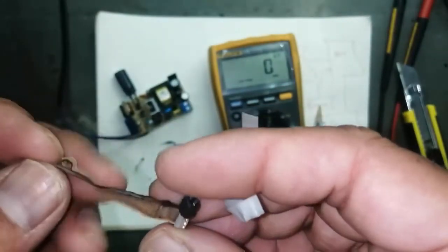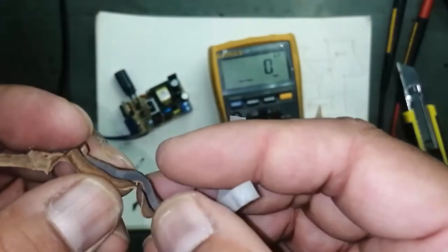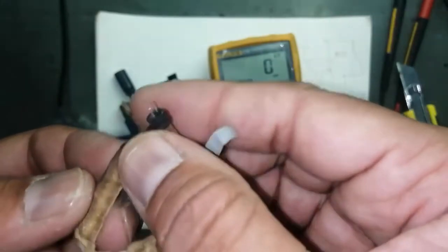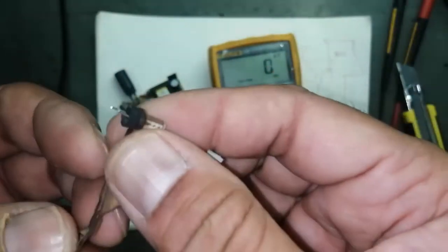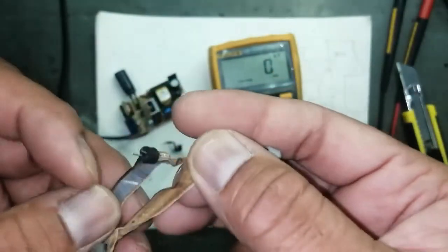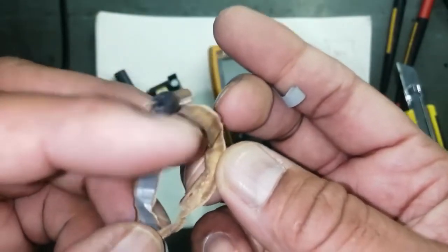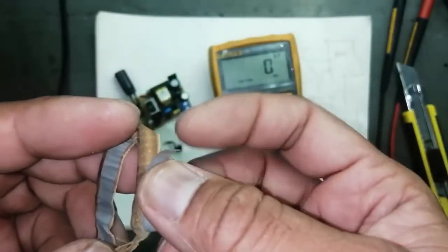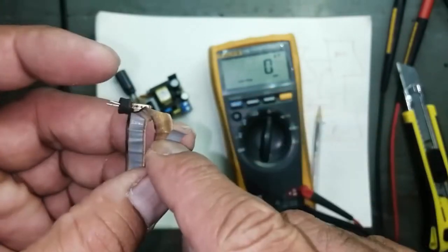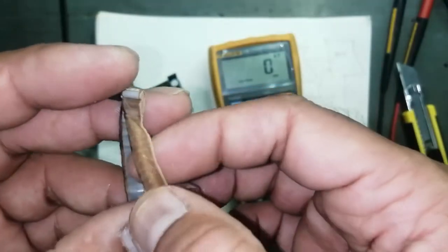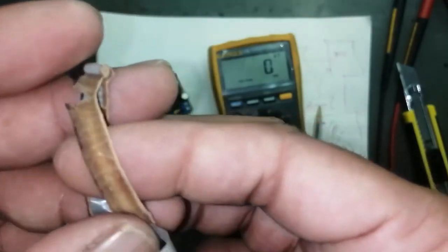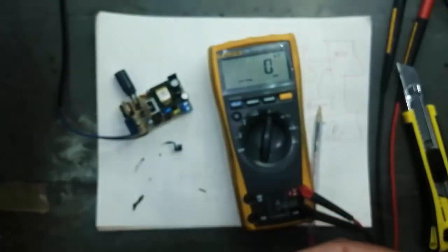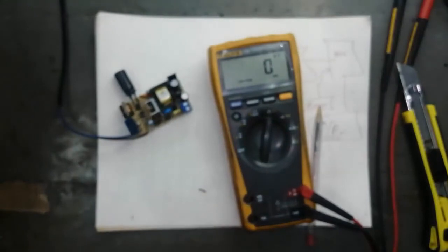So due to leakage, this is discolored. The color changed due to sparking inside. This was the reason. The internal insulator of the capacitor was short circuited. Between these 2 plates, this metal and this metal, there is an insulator. If we see this insulator, it has a bad color. So it was the reason for the fluctuation in the voltage.